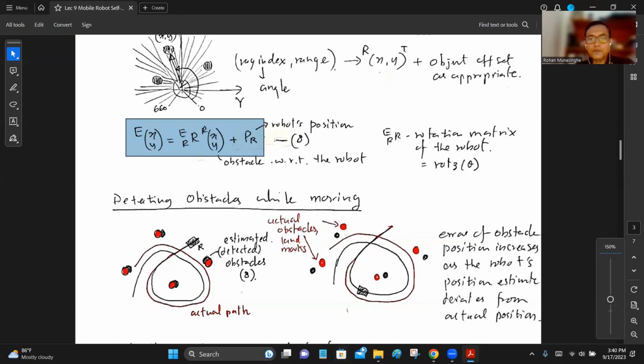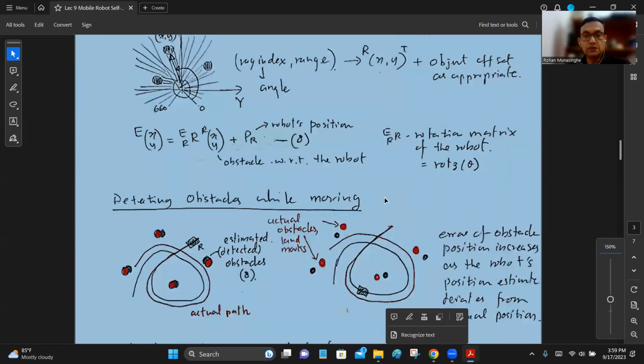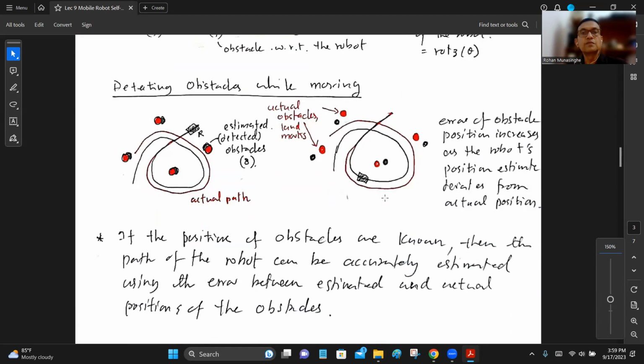All right. Now we know what we have to do here to improve the accuracy of localization, to find out the actual position of the robot, which means we want to bring the black path over here, this is the estimated path, as close as possible to the red path over here, the outer curvature here. When we do that, the black landmarks will gradually get closer to the red marks. Okay? So you need to have that understanding right now.